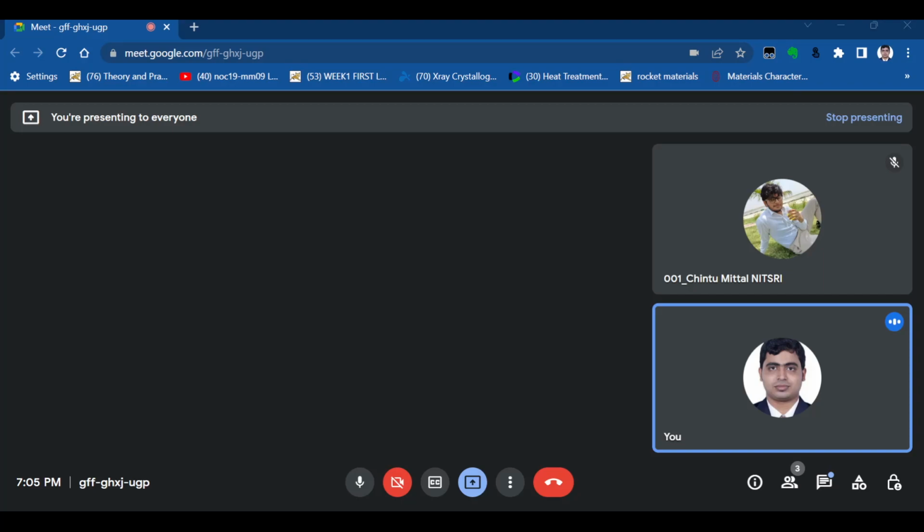Okay, if you have to calculate fraction of liquid, you take the opposite direction. If you have to calculate the fraction of solid, then you go in the opposite direction. So for liquid, we calculated this BD divided by AD. For solid, we calculated this AB divided by AD.